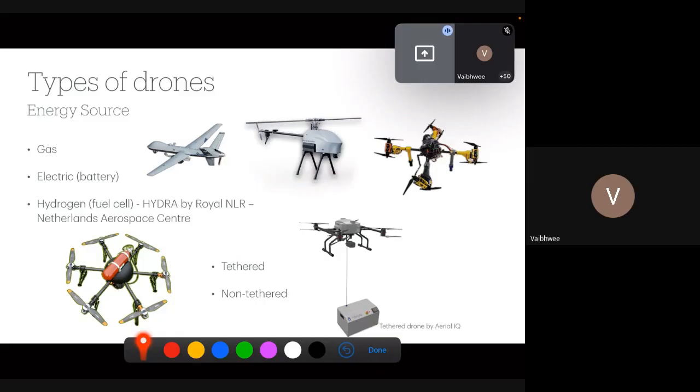These days, there are drone setups with a hybrid kind of mechanism wherein the drone is run on fuel. The fuel runs an electric generator set. So there is an engine that drives a DC generator. This engine basically consumes either ethanol or petrol, and this DC generator produces the energy that is required to drive the electric motors.